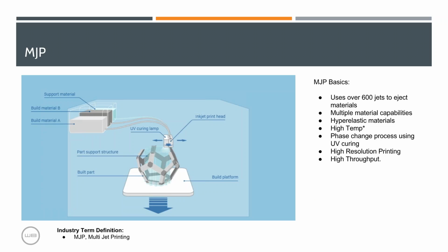The print heads are also extremely wide, which gives you an economy of scale benefit. If you have one part that takes 4 hours to print, you can fill up the entire build plate with the same part, whether you can fit 100 of them or only 4.